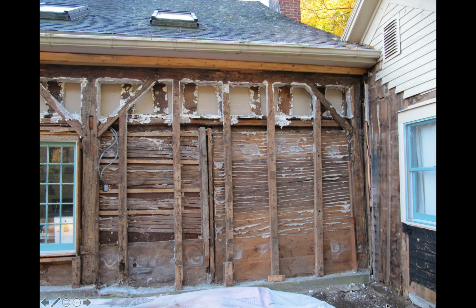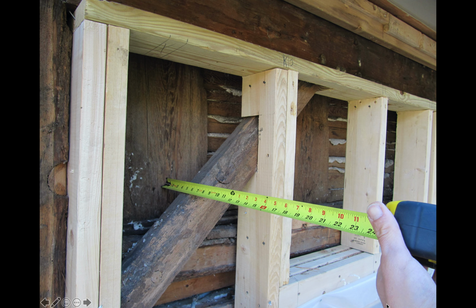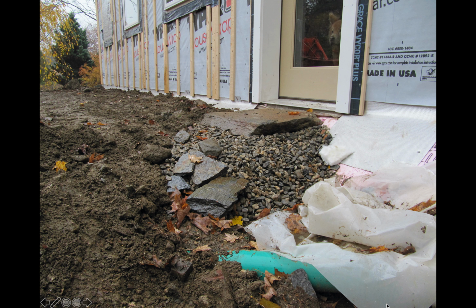So you can see here, we cleared it all out. We installed wing insulation, and then we rebuilt the structure, and we built the walls a bit deeper. This has allowed us to add more insulation, and then on top of that, we added rigid insulation and a vented rain screen. We are now getting into the point where this is like what a real building scientist would want to have happen to a house.